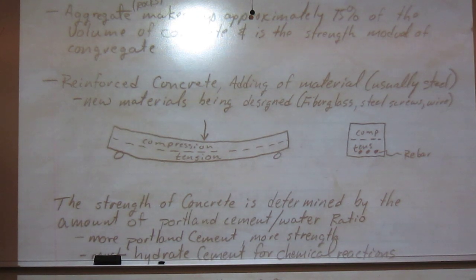Another nice fact: I did a lot of blasting in mining, so I blew stuff up. Loved it. Got paid a huge amount of money to go blow stuff up in the sand pit. But anyway, when we blew up rock, you don't break it with the explosion. The explosion actually compresses the rock, and then as the gas leaves the hole, the rock comes back into that hole and goes into tension. That's when the rock breaks. So it's not breaking during the explosion, it's breaking after. And this stuff's the same way.